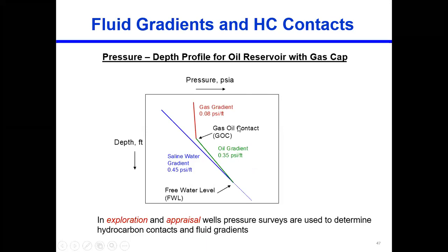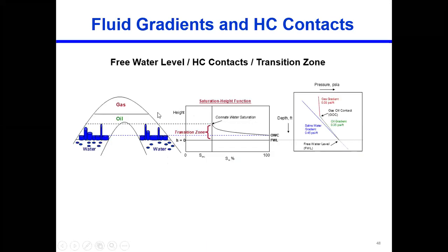Now, because of their density gradient, the pressure is different for the gas, different for the oil, and different for the water. The pressure gradient for the gas has something like this shape. For the oil, it has a shape like this one. From the experience, we know that. And actually, the software automatically detects it. So based on that MDT tool that I showed you before, we create the profile with pressure. This tells us which kind of region we are going through. Are we going through the gas, oil, or the water?